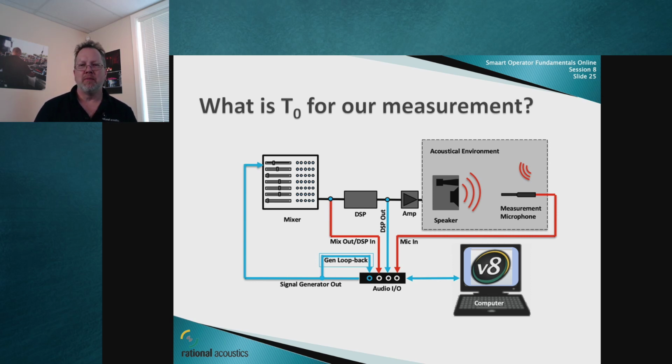And that can be dangerous, because you could have EQ inserted and be blind to its effects. So one of the things you're going to want to do is find a way to get a pre-DSP, pre-system DSP point to grab as your reference signal. Like I said, there are so many things that can happen in here. One of the worst things in the world is to have EQ or compression inserted in your measurement channels, because that's just going to throw you off in your measurement. But that's the way of the world now.